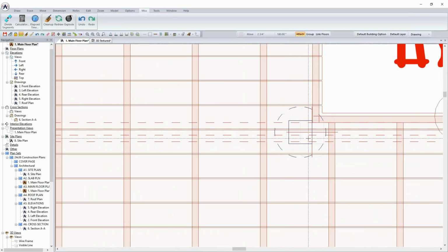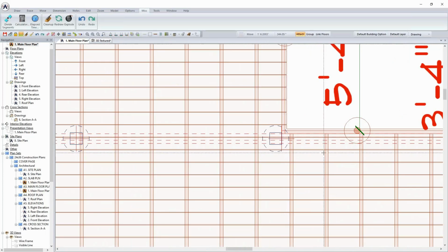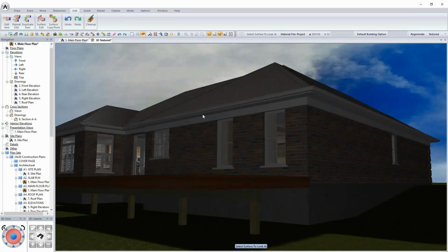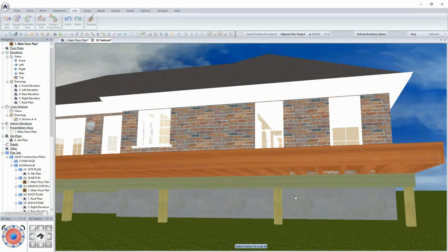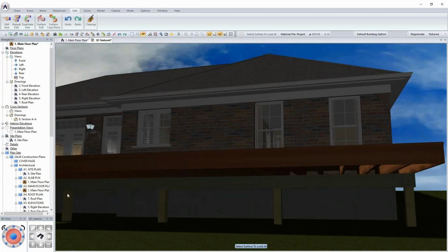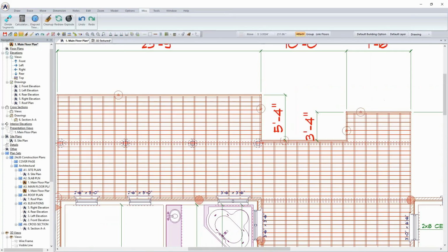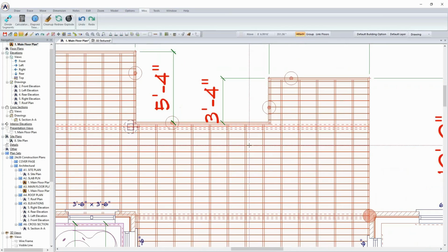Now, you can always move these where you want them to be specific. But the key to this is, first of all, the construction points allow me to lay posts out at equal distance without having to pull all the dimensions off initially. And secondly, the Draw Select tool will allow me to now draw the exact same post, the one that was edited, multiple times, in this case, using all of the editing properties that were assigned to that actual post. And so now, just to carry on, I can use the move and copy if necessary, if that's what we want to do.